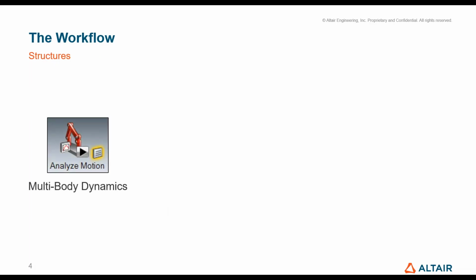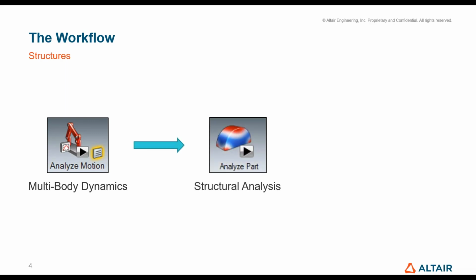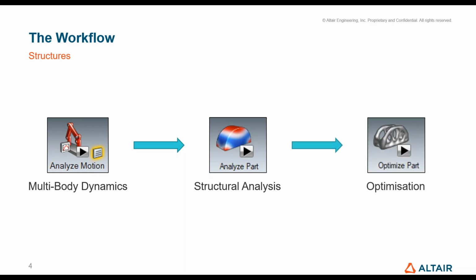The workflow in itself, when we're looking at a structural analysis, we start off with the multi-body dynamics, to understand how parts move relative to one another. You then take it through for a structural analysis. Based upon the way they move, how do they affect the stresses in your parts itself? Will it break during its use? And obviously if it doesn't break, and you know for a fact that you can make it lighter or you want to optimize it as well, you can conduct an optimization.